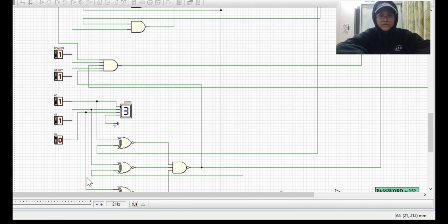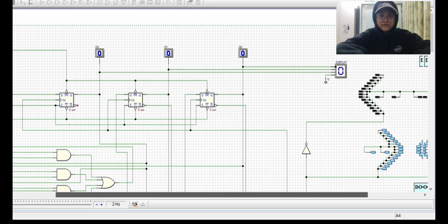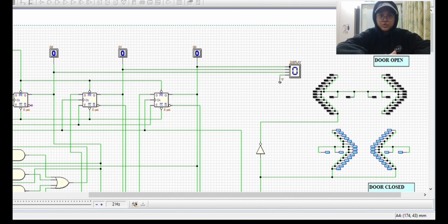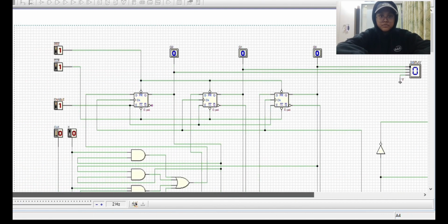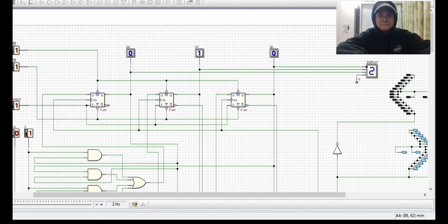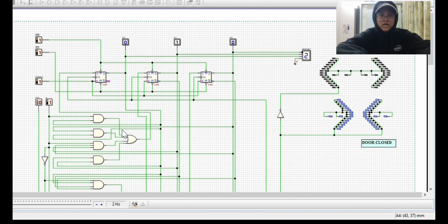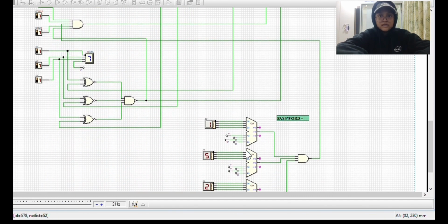Observing the LED indicators, the one signifying the closed door illuminates when not yet at level 7, such as at level 1, 2, 3, 4, 5 or 6. Conversely, the LED indicating the open door activates upon reaching level 7. This is determined by the comparator, which outputs 1 when the selected and current leaf levels are different and 0 when they are matched. To properly interface the comparator output with the door open LED, it is necessary to invert the comparator output.